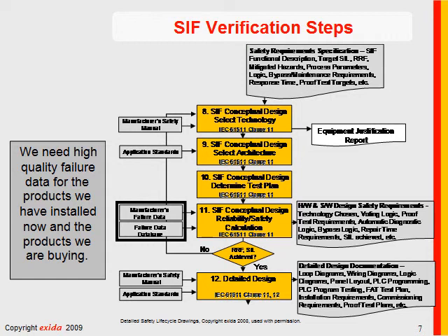It can be done on a design example basis, but to get maximum flexibility and to optimize the cost of every safety installation, a risk based performance approach can be used. The advantage of that approach is we can really do a fine job optimizing a design for a particular site. But we must have good failure rate data in order for this whole approach to work.